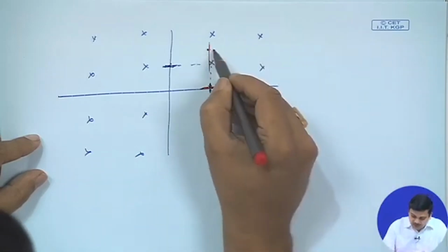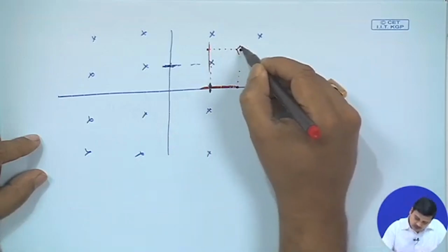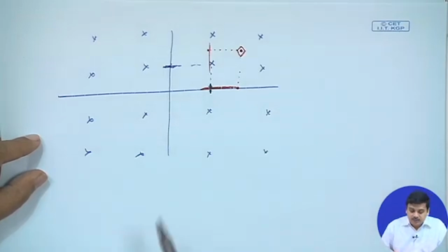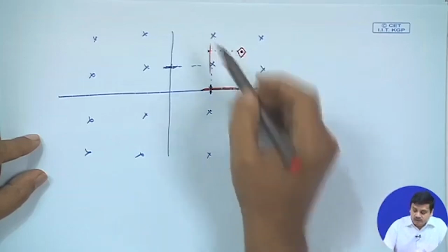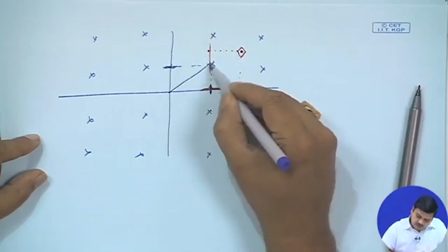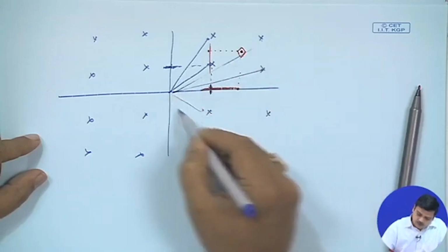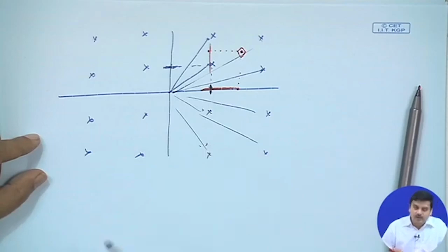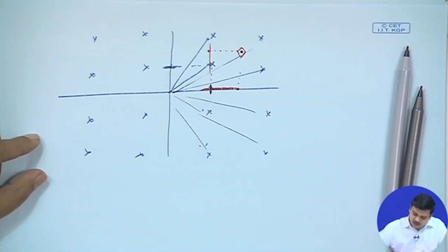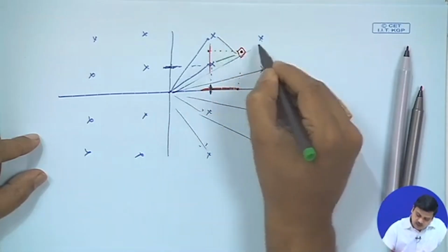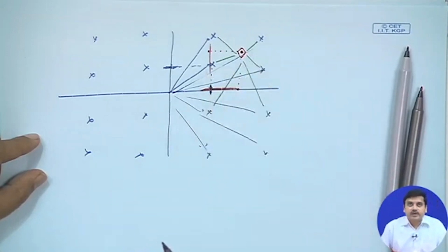So, the received signal would be at some location which is here. The minimum distance metric tells that you have to compare the distance with all possible vectors. So, these are the different vectors, and you have to see the distance of the difference, which is the nearest distance to it. The shortest distance we identify as the outcome.